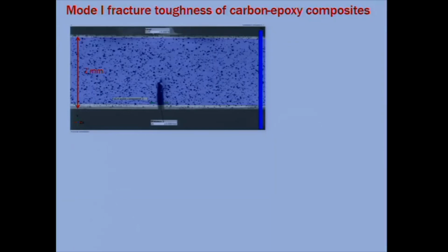You may know that. But basically, that will give the strain map of the whole deformation. But what you need to look at is just the crack. I load the specimen, just load it and unload it so that I can see the crack much more clearly rather than just load it very quickly and you couldn't capture the crack easily.